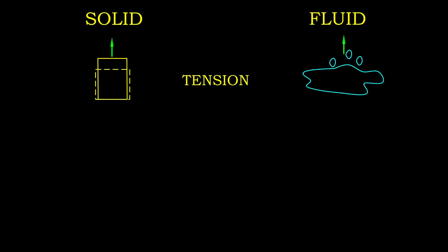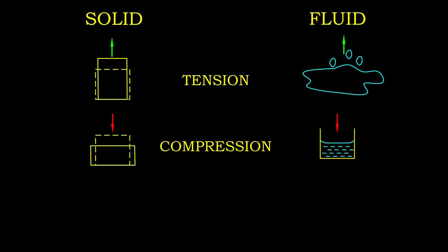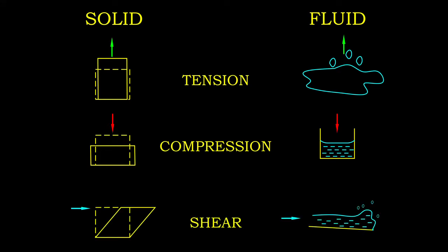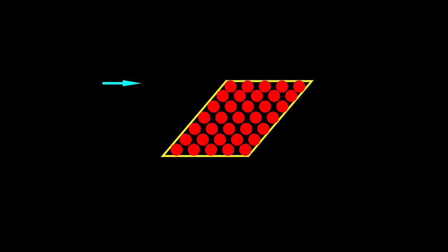When subjected to external forces, fluid responds differently from solid. The tensile strength of fluid is zero or negligible if it exists. Compressive strength exists in fluid if and only if the fluid boundary is fully restrained, which usually takes place when it is inside a container. When subjected to shear force, the fluid layers displace and cause the fluid to deform continuously as long as the force is present. Most fluids are Newtonian as they obey Newton's law of viscosity.